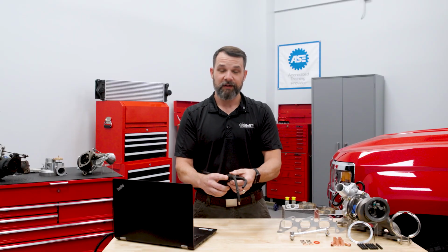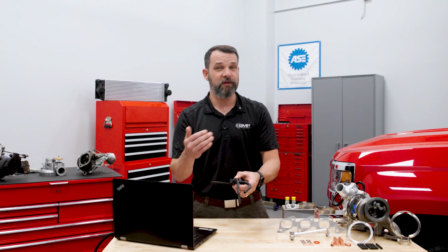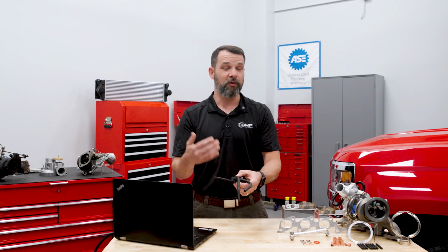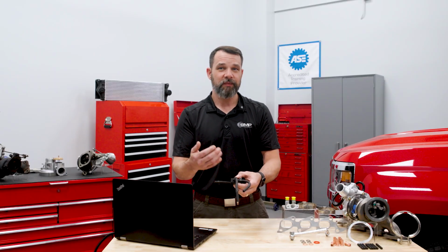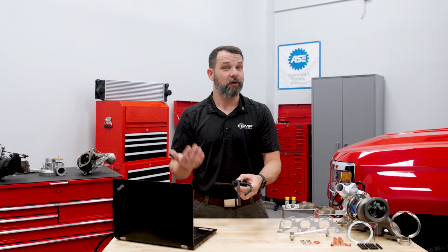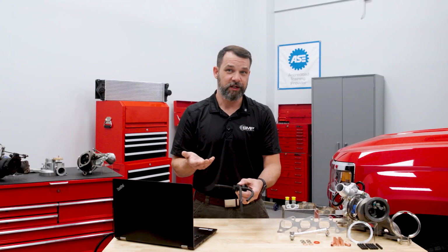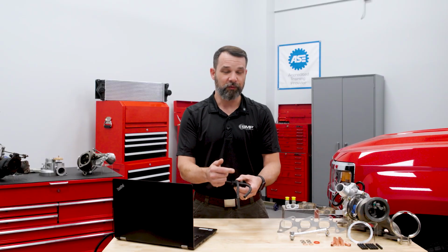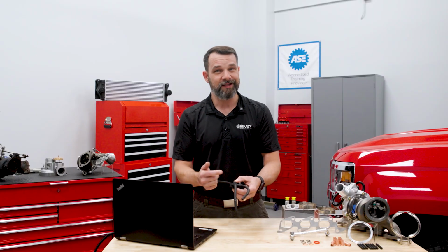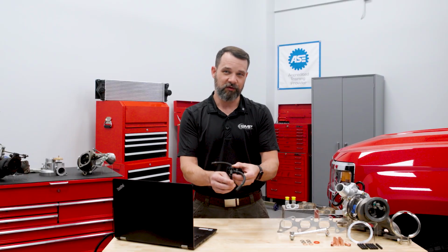So again, it's a side note, it's probably not something you're going to run into a whole lot, but when we come to visual inspections and things that we can do to more quickly diagnose an underboost situation, and we look up and we see there's a lot of skid plates missing or engine covers or really any type of protection for the engine and transmission whatsoever, you might want to go look at these hoses first, because there's a really good chance something has cut, nicked, or hit this, and that might be all that we have to replace is the solenoid itself.